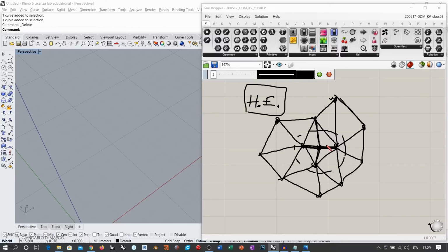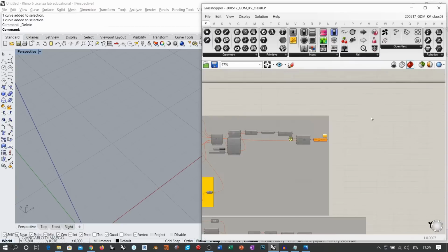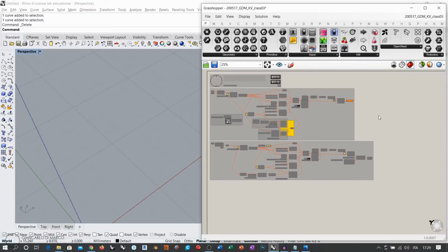And once you do this, if you need more resolution here, you can split this edge, and you have another two triangles and another two triangles. So you are increasing the resolution, but locally, and not necessarily all around the desired area. So the half edge representation is better for this kind of simulation.